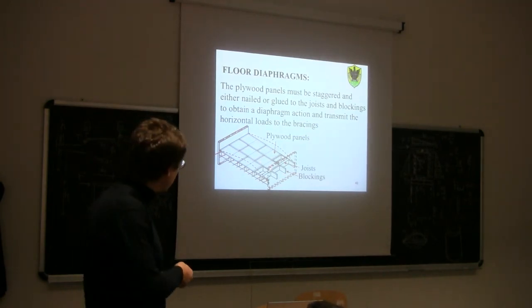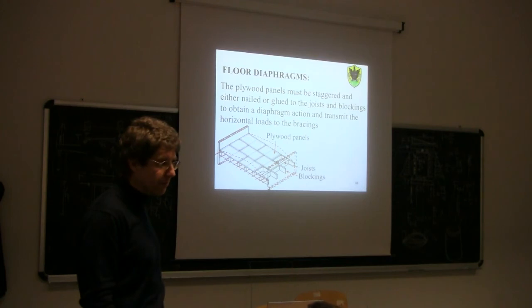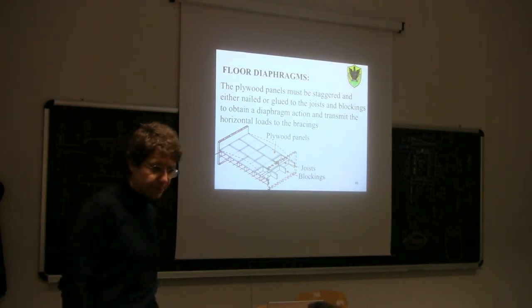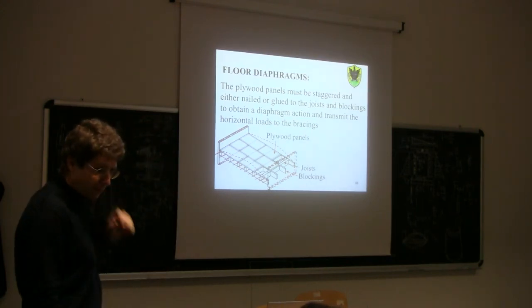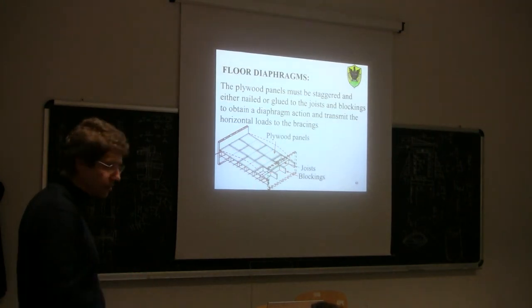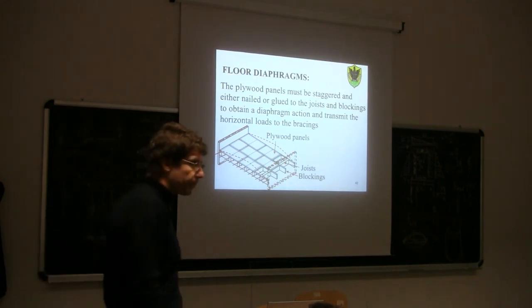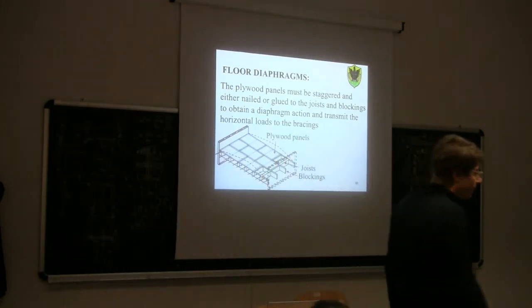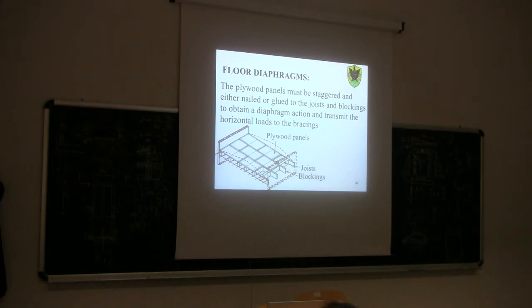Which kind of forces do we expect on the nails? Shear due to what? Yeah, but are we sure that the permanent load is going to load and shear those nails? Compression. Yes, but compression, I mean, in terms of compression, we could also remove the nails. Suppose that I remove the nail, compression is just due to contact in the end. We have some little bit of it. It's clear that I couldn't do this, but strictly speaking, these nails are not very much loaded.